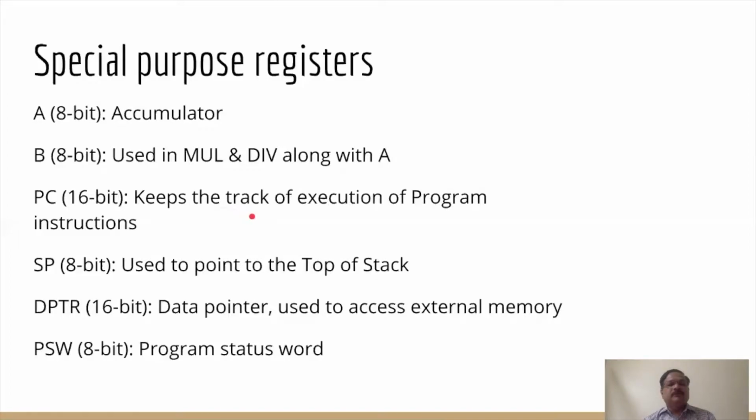But whenever there is a branch, let us say calling a subroutine, or whenever there is a jump instruction, or whenever an interrupt occurs, in those situations the PC contents are updated with the new address and the execution is transferred to the subroutine, either the interrupt subroutine or whatever subroutine is called, or using the jump, go to the branch address.